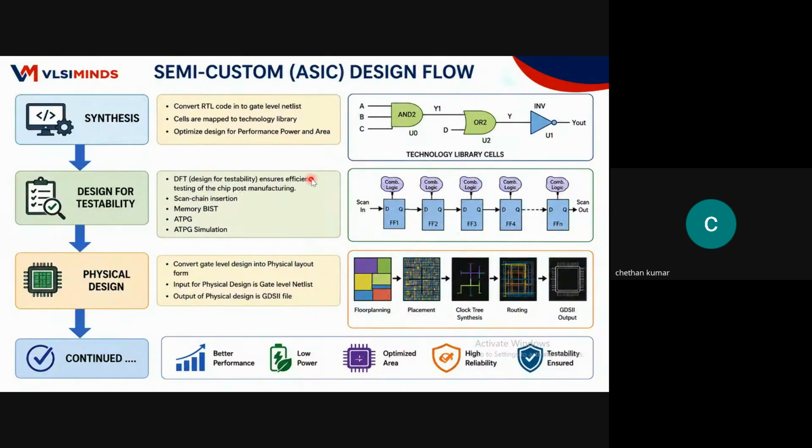That will be done by using our design team. So that is called design for testability. Many of them will be thinking that design for testability means it is a tester's work. No. The DFT team is totally responsible for design only. So designing, adding extra logic inside the design, which makes it easy to test the chip even after manufacturing.